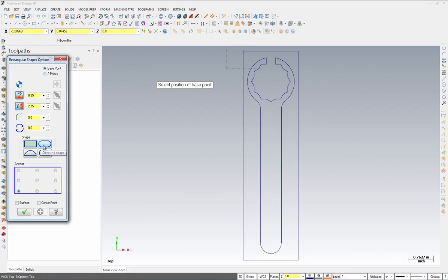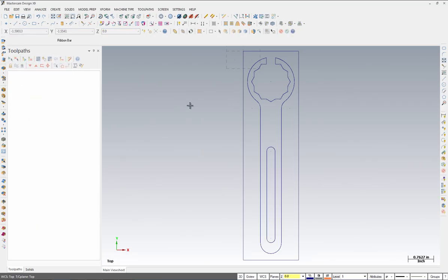Ensure that you have this shape right here, and make the anchor point the bottom middle. You will need to go ahead and stay in this dialog box and change the fast point to indicate where to put this shape. Insert the value 0.825, separated with a comma, and then minus 5.5, and hit enter on your keyboard. And select the OK button. Your part should look as shown.